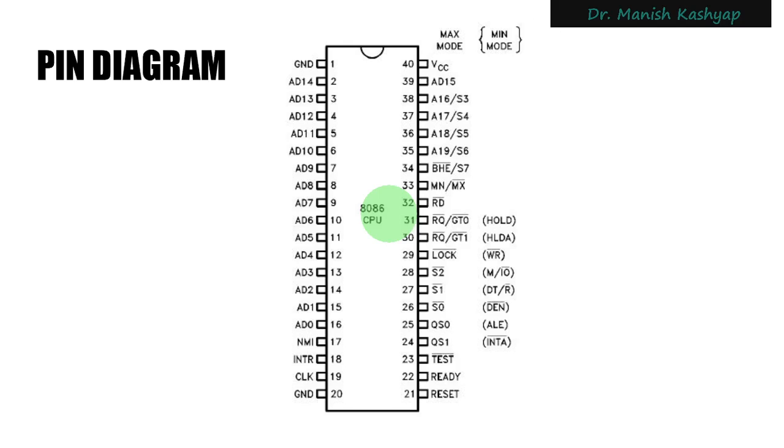there is something called a math coprocessor. The math coprocessor can be used with this processor. It is called a coprocessor because it operates together with this processor. That processor is 8087. This is 8086, and you can have one more processor which has dedicated operations for mathematics. That processor is called the 8087 microprocessor, and it operates together with this CPU as the main CPU, right?